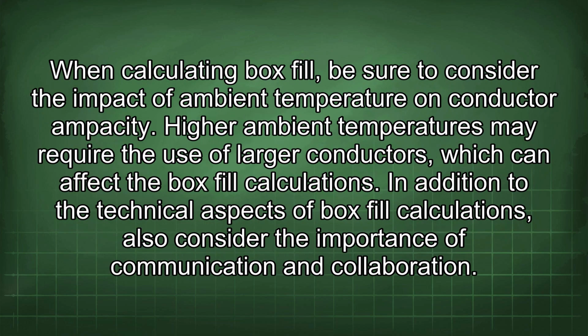When calculating box fill, be sure to consider the impact of ambient temperature on conductor ampacity. Higher ambient temperatures may require the use of larger conductors, which can affect the box fill calculations.